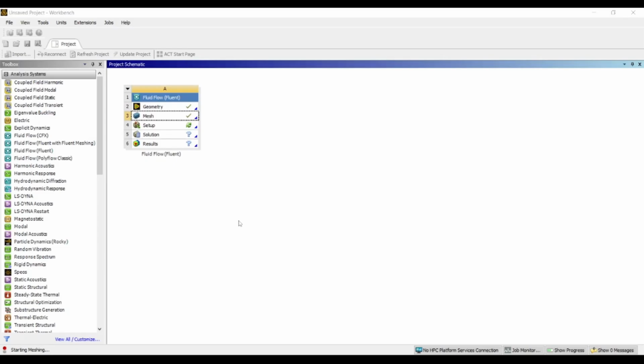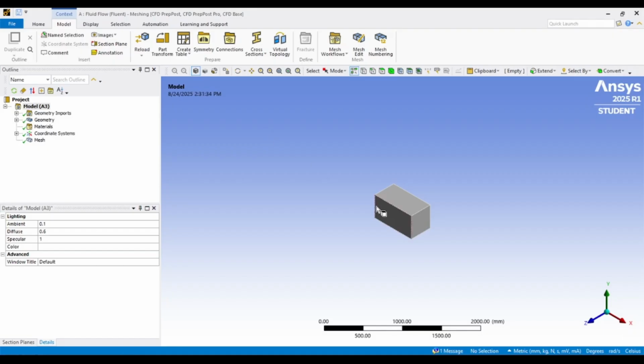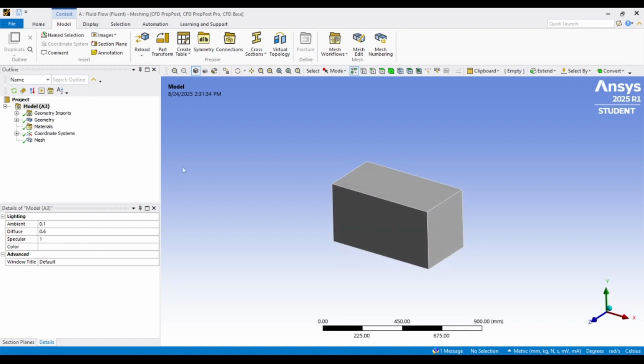Next, display the pressure contours. You'll observe a high-pressure region at the front stagnation point and a low-pressure zone at the rear, causing a drag force on the cylinder. You can also plot velocity vectors to visualize the direction and intensity of the flow, or create streamline plots to see how the fluid paths bend around the cylinder and swirl in the wake.